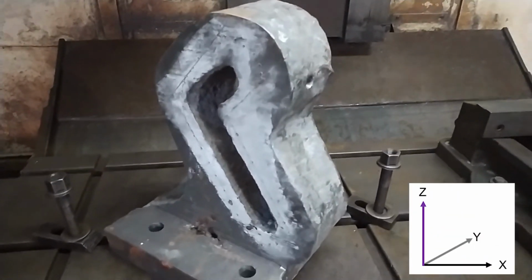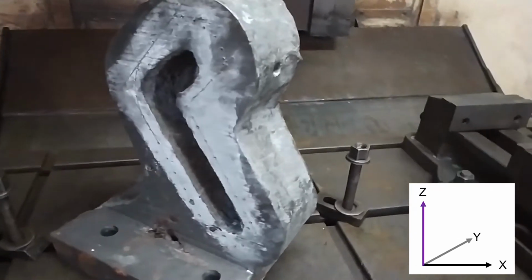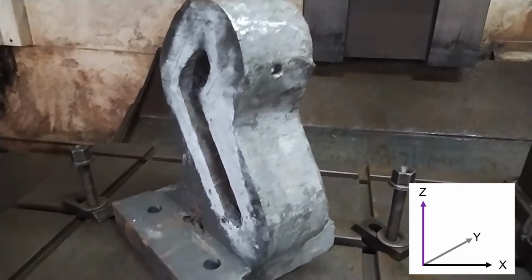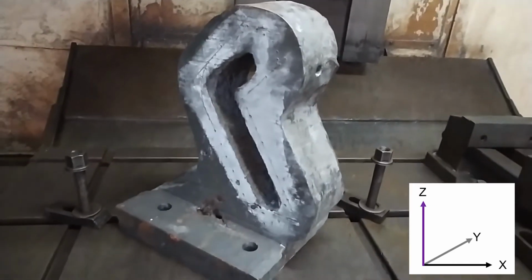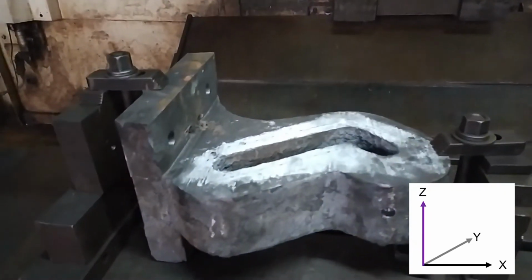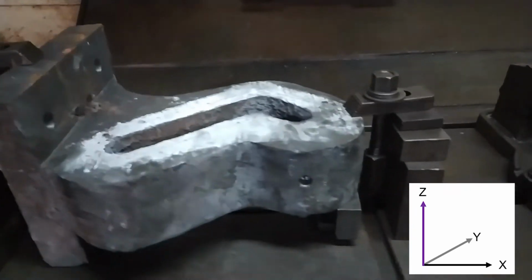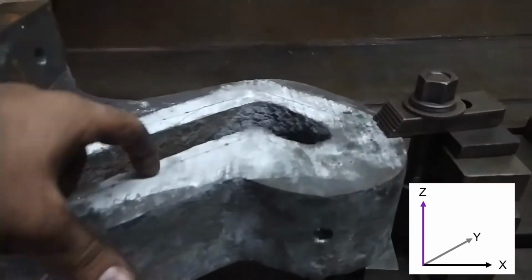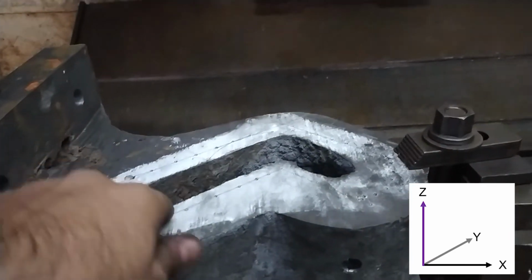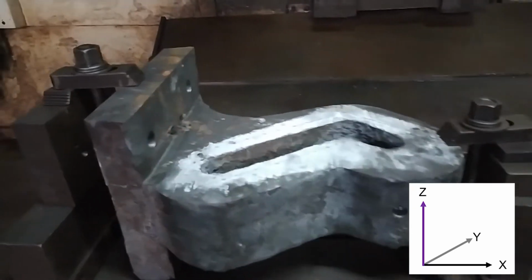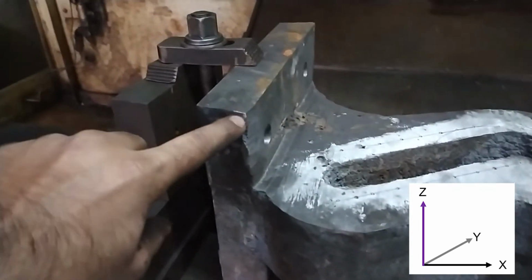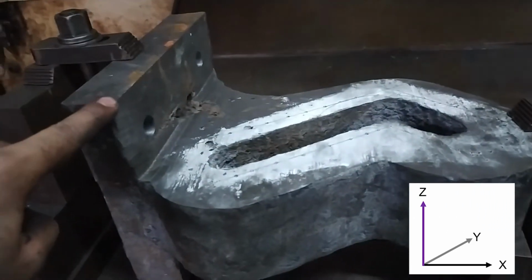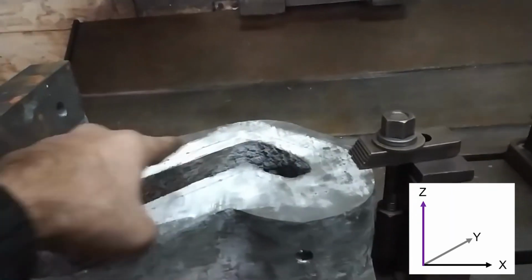So the job is on the bed, and as you can see there, I'm going to place this job horizontally so that the marked surface is parallel to the XY plane and the slot is facing towards the Z direction. So this is the way I want to place the job on the bed. As you can see here, this is the marked place where we have to perform the cutting operation. Before doing this, we have to set XY0 at this point, so that by taking this as a reference, it will perform the cutting operation.